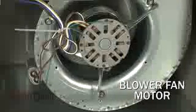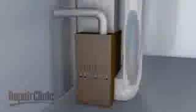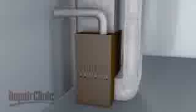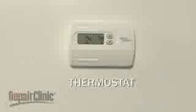The second air system uses a blower fan to draw air through the return vent, blow it past the heat exchanger, and force it through the home's venting. The room air is then drawn back through the return, and the airflow cycle continues. Once the room air has warmed sufficiently, the wall thermostat signals the furnace to turn off until the room temperature decreases. This process can be broken down into four main factors: temperature control, ignition, combustion, and air circulation.